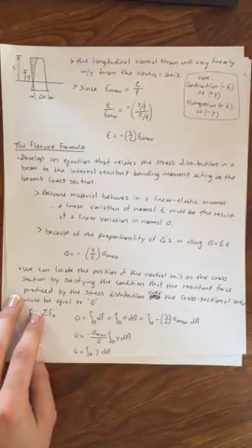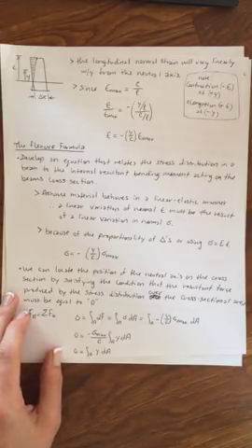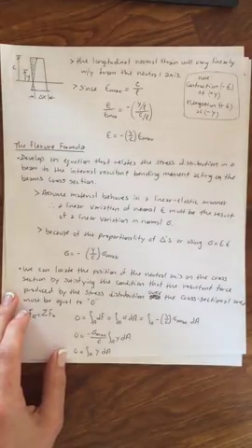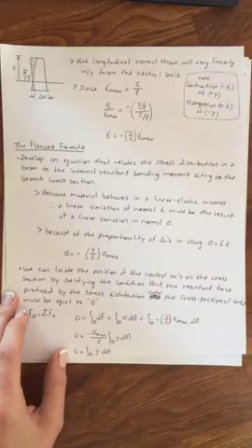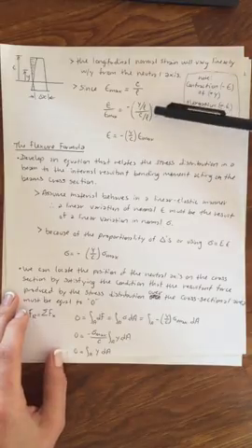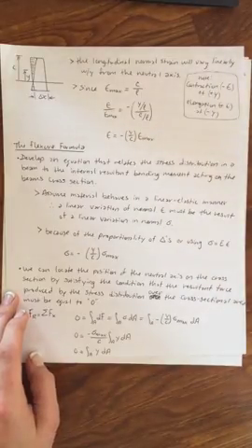Since the maximum strain is equal to c over rho, where c is just the distance where maximum strain occurs, the longest distance away from the longitudinal axis, we can use our strain relationship that we just found along with the maximum strain to determine that the strain equals negative y over c times the maximum strain.